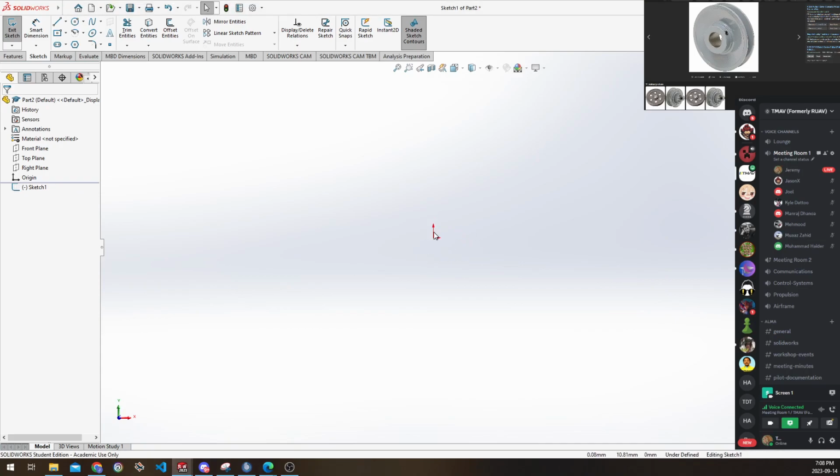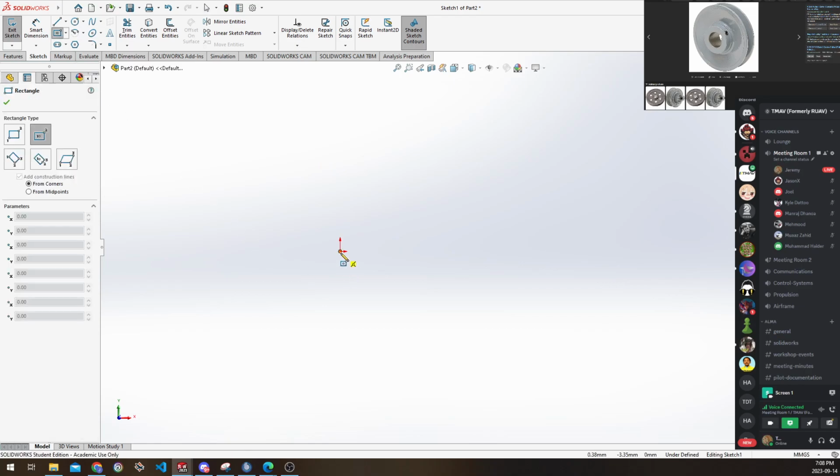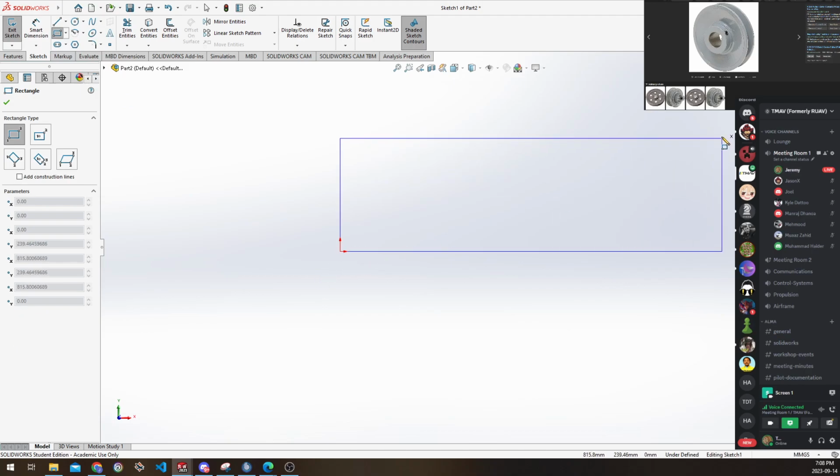There's a few options. I'm going to define the pulley as the center of this origin going up will be the height of our pulley, and the right side going out here will be the kind of inlet, okay? So what we're going to do is I'm going to grab a corner rectangle, define the bottom left corner as the center origin, and pull the rectangle up here,